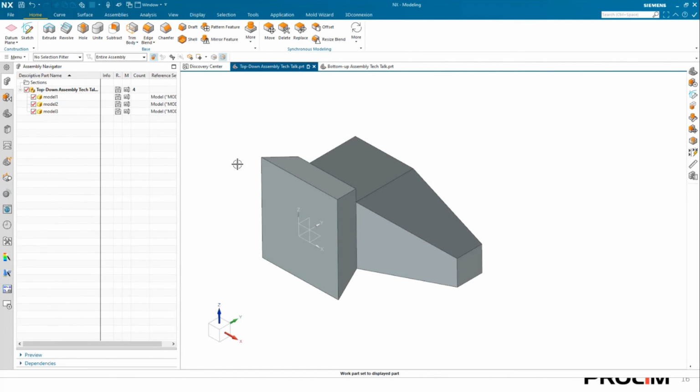Hey, Bilal, just real quick to help you on that. When you were creating it, you were projecting the curves. If you would have included the curves, it would have stayed associative, by the way, on the sketch command.